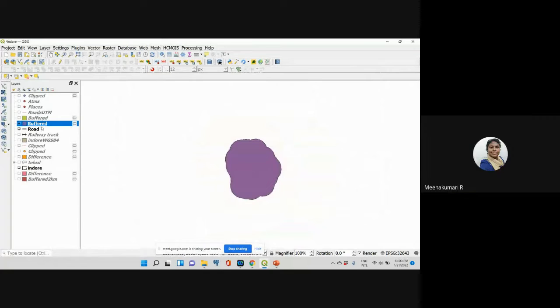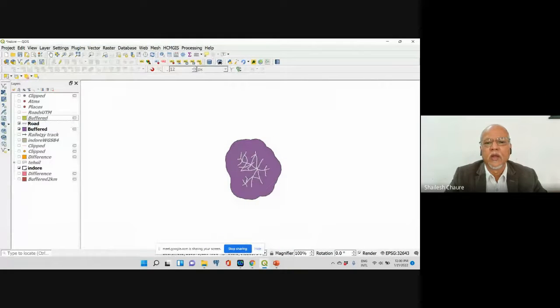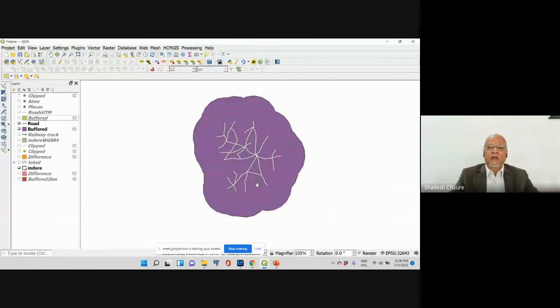This is our road. Of course, you can compute the appropriate degree equivalent to the distance in meters or kilometers you need. But actually, the latitude, longitude, or geographic coordinates are used on a curved surface. So the calculation of the distance will vary with latitude as you move from the equator to the north pole or south pole. The formula of calculation will vary.